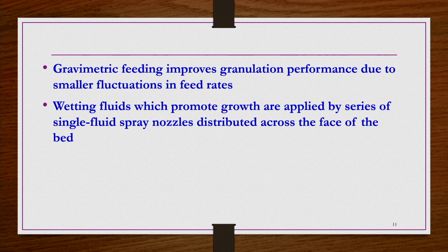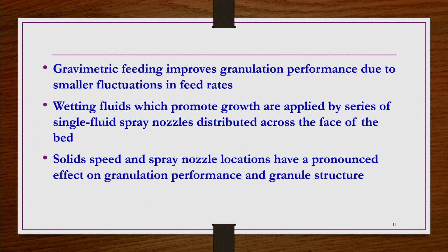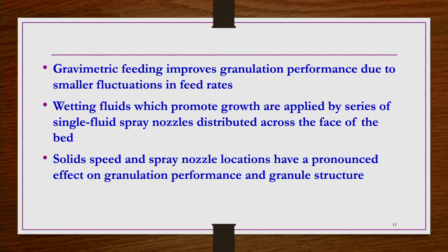Wetting fluids which promote growth are applied by a series of single fluid spray nozzles distributed across the face of the bed. And then the speed at which solids are entering, and the location of the spray nozzles, are going to have a significant effect on granulation performance and granule structure, because the feed should not be coming at a very slow rate, so that a large amount of binder solution is coming, and when they are mixing, a kind of slurry is taking place rather than granulation. So, that should not be there.